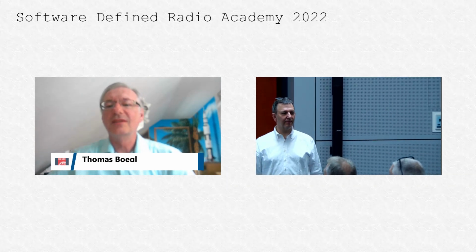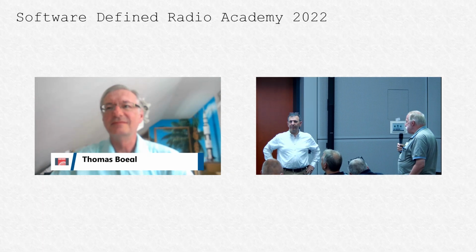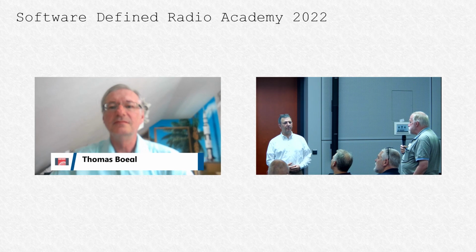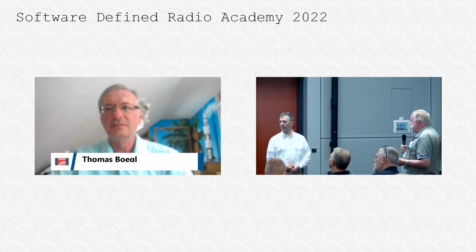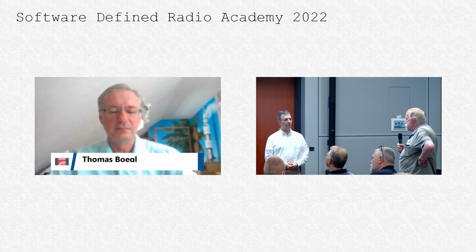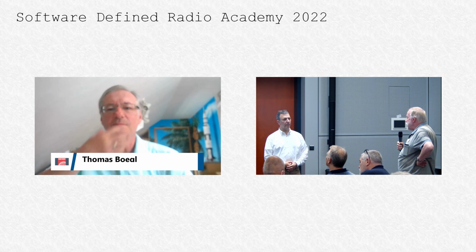Thank you, Chairman, and good afternoon, everybody. I'm Sven, OZ7S, and I remember a presentation at Friedrichshafen 3 years ago, in 2019, about the same subject, and I guess one of the conclusions was that the determining factor between using a wideband receiver, direct sampling at the RF, or an intermediate frequency concept would be something like the phase noise characteristics of the oscillators in the receiver. Could you elaborate a little bit on that, please?